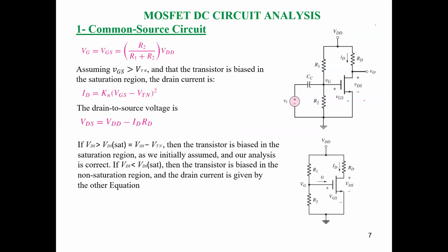In order to apply this type of pulses to make the analysis, or to apply a current to flow from the drain to source, you need to make what's called DC analysis. DC analysis means I will apply a DC signal to our switch. So this means no AC component will flow in our circuit. This is the meaning of having DC analysis.